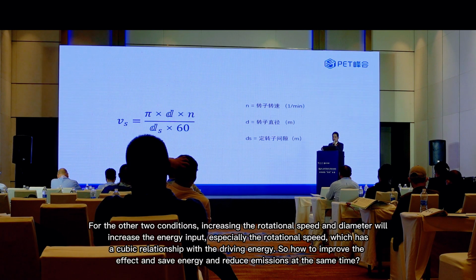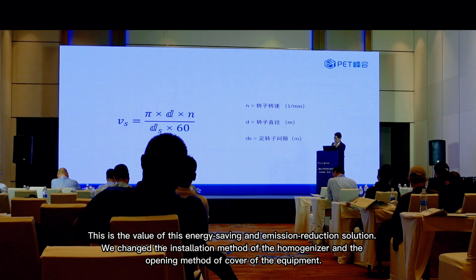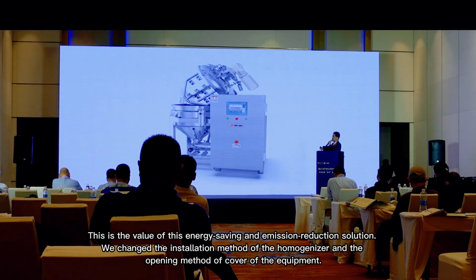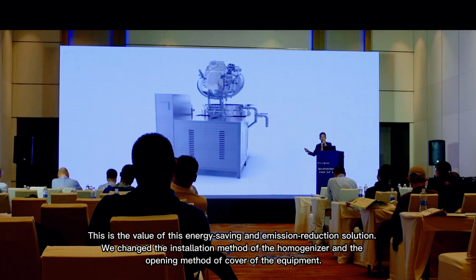For the other two conditions, increasing the rotational speed and diameter will increase the energy input, especially the rotational speed, which has a cubic relationship with the driving energy. This is where the value of energy saving and emission reduction comes in. We change the installation method of the homogenizer and the opening method of the cover of the equipment.